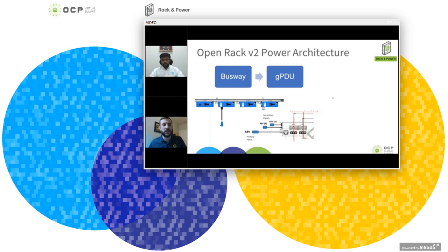That means that depending on which cable is in the drop from the busway, which could be an IEC 309, it could be a California standard, or a NEMA plug, the PDU that you need gets tied to that specific connector. From the PDU, you then go down to the power shelf, and in the power shelf, we have a few different SKUs as well for the varying power densities. So whatever amperage you need your power shelf to run at, you need to pick the specific SKU that can be appropriate for that architecture.